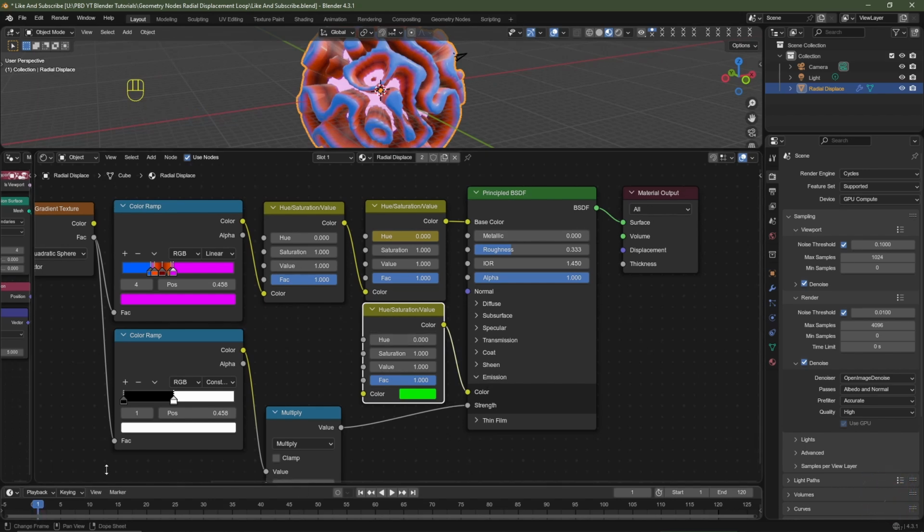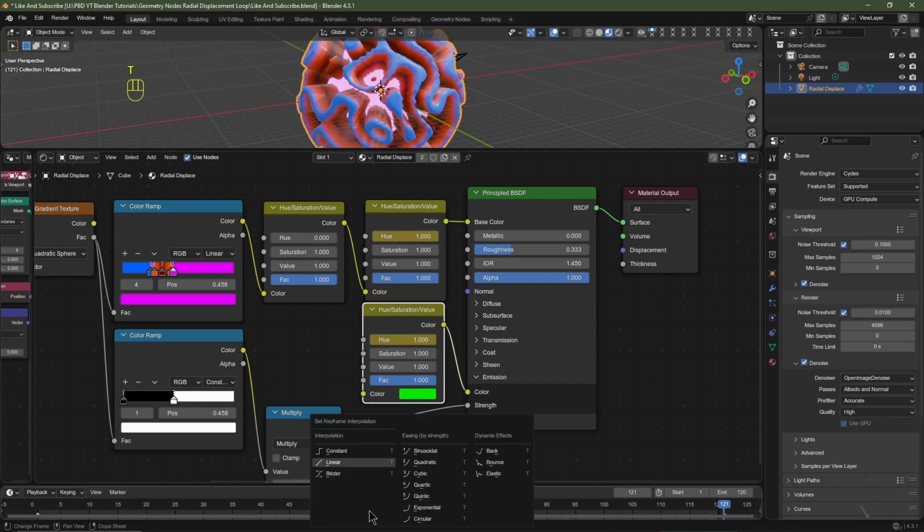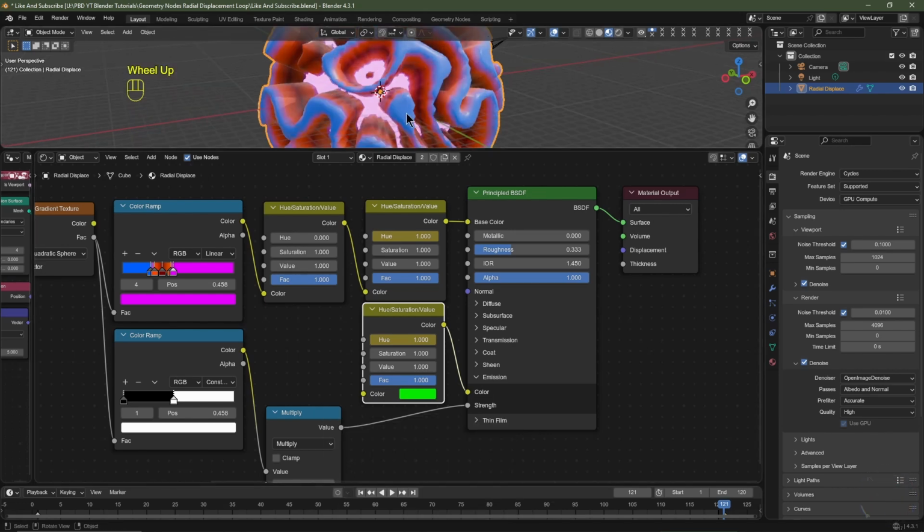And on frame 1, with your hue set to 0, I'm going to hit I. I'll then skip to the last frame. I'm going to skip one more frame, and I'm going to set the hue to 1. I'll then hit I, and then again hover my cursor over the timeline. I'm going to hit T and change the animation interpolation type to linear. So now our emission should change color as well. They should work as complementary colors the way I've made this.